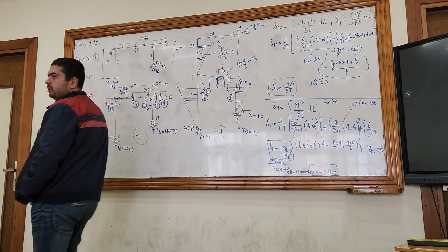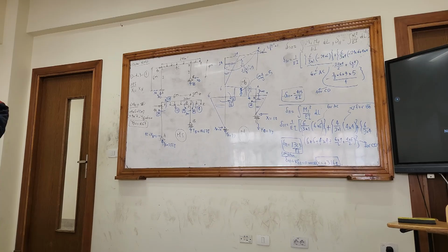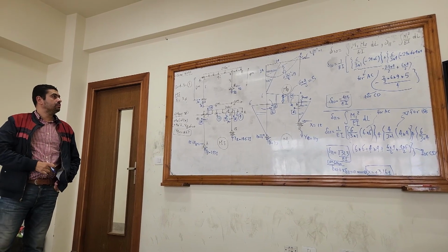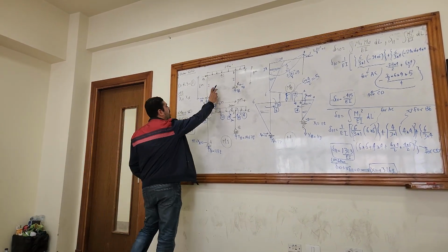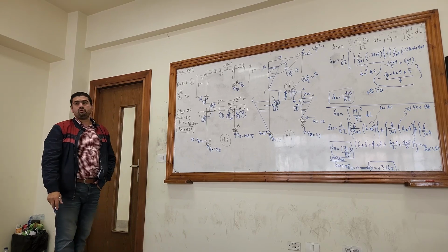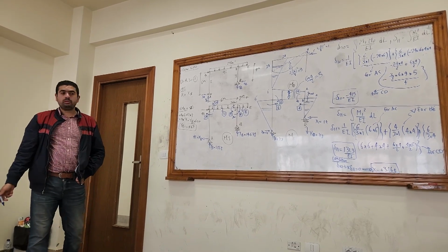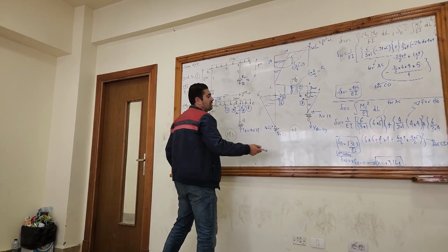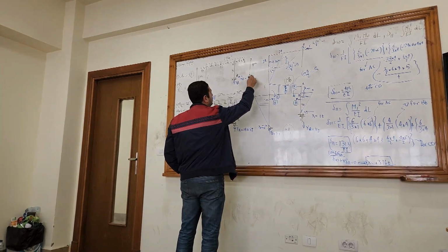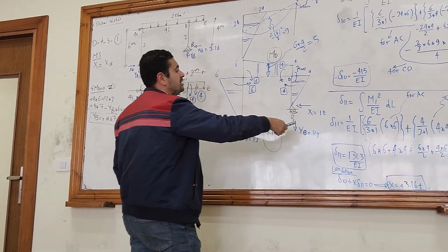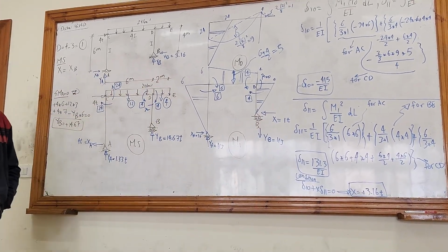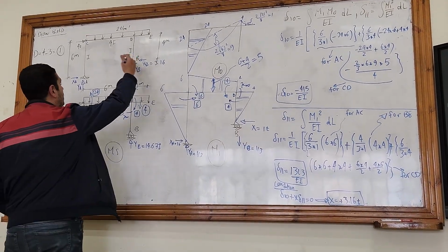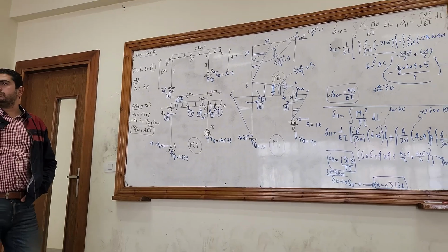Now I have two ways to draw the final bending moment diagram. The same way as in the superposition, the main example, the one that was indeterminate. Now it's not indeterminate. What was x? X was xb, right? So xb equals 3.16 positive. What does the positive mean? It means that my assumption was correct, so it's to the left. So this direction. So 3.16 to the left.